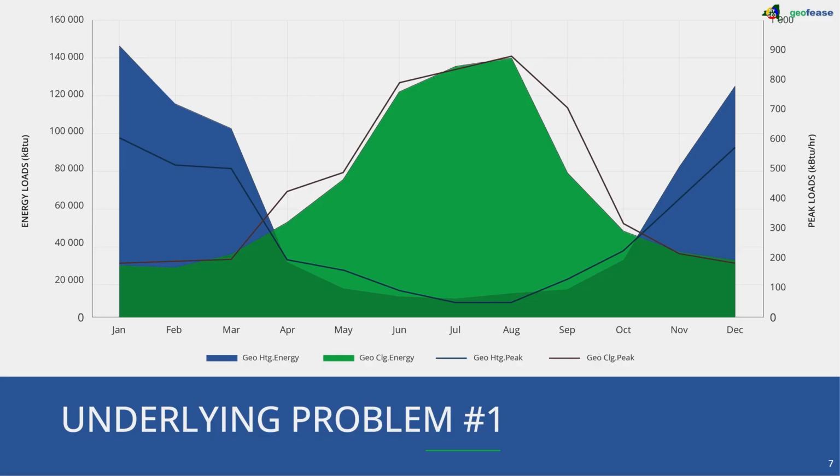systems. So when you get a commercial ground source heat pump project, you typically start with a building energy model, right? You upload that building to the computer to try and understand the hourly heating and cooling loads for that system. But the problem is, again, even if you're the best energy modeler in the world, it's a static model, and the GeoExchange system is a dynamic system. It's changing every year. So you do your 8760 hourly model, you do your thermal conductivity test, right?